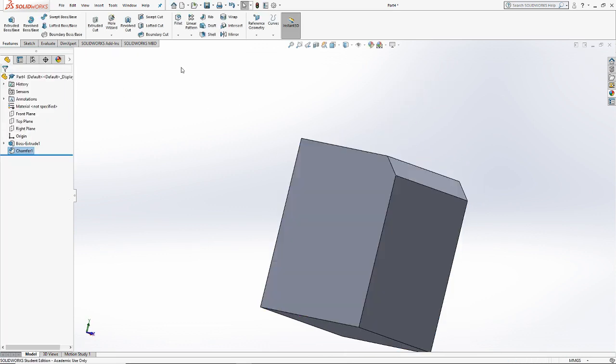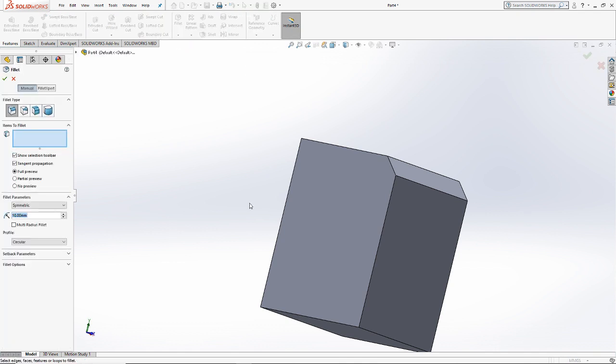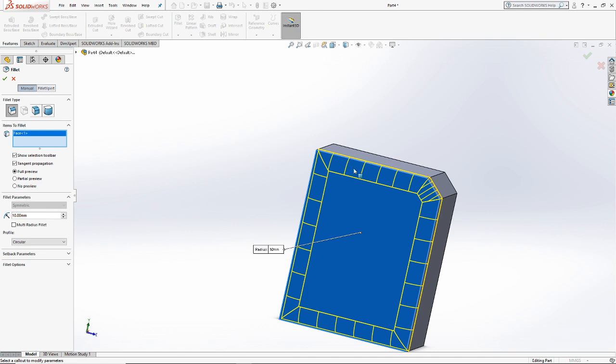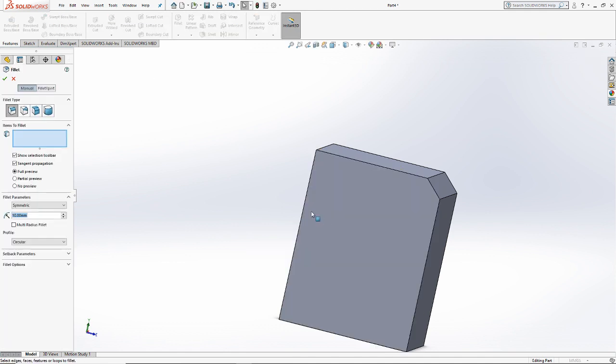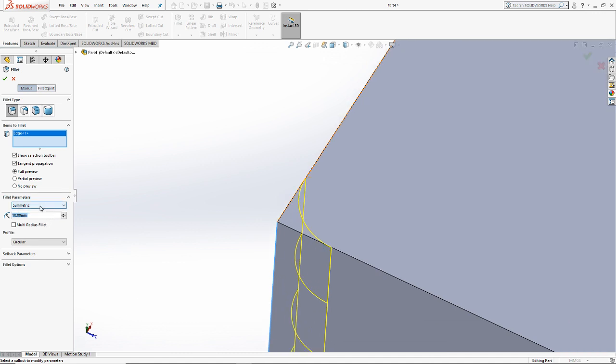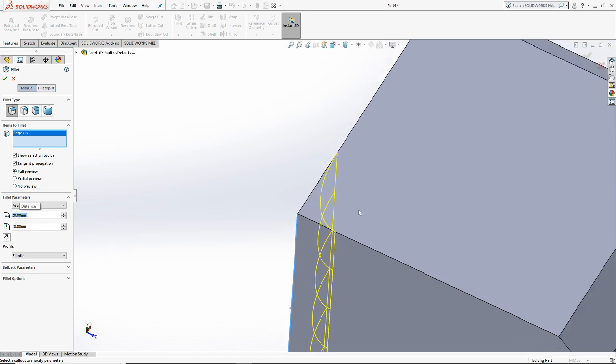I will also point out that underneath the fillet tool, you have some interesting geometry options. If you wanted it to be a symmetric fillet, so that you ended up with a nice arc, for example, you can use the symmetric parameter when you're generating a fillet, but you can also create asymmetric fillets that are longer on one side than the other.